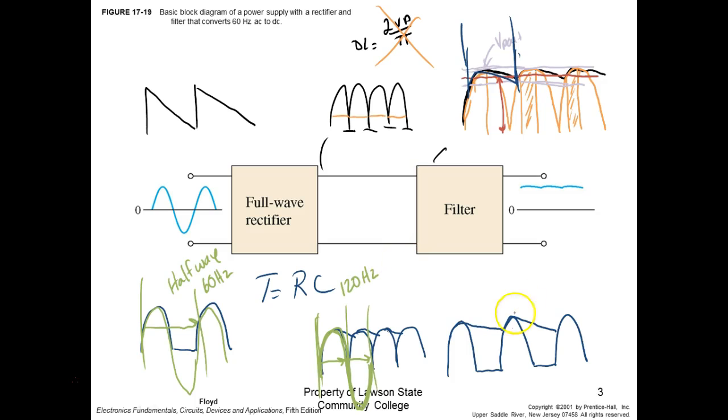So here, the capacitor is going to have to run the load for 16.666, or 16.7 milliseconds, for 60 hertz. The airplanes I worked on, and this got me in trouble one time, ran at 400 hertz. So right off the bat, that means my capacitors could be a lot smaller in my power supplies, because they didn't have to run the load hardly any time at all, right?